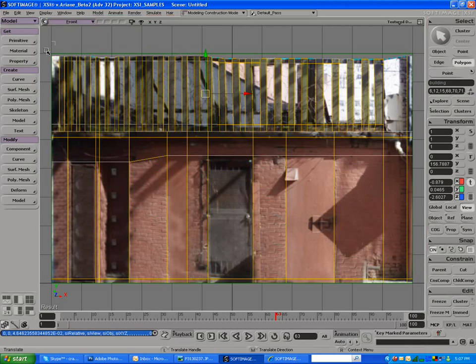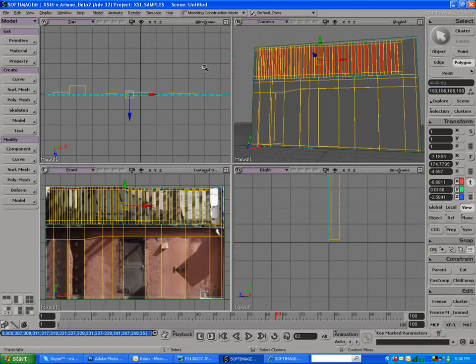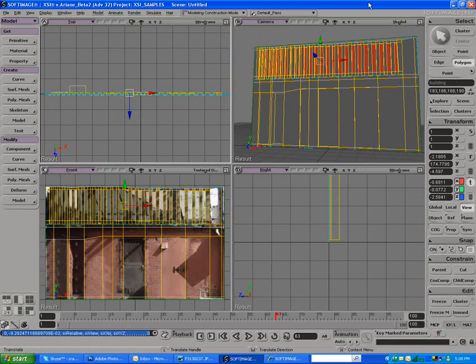So go to Control, and we'll just select over the whole lot there, and then we'll do Control Shift, get rid of the end one we want to ignore, and then also the top, and Control Shift on the bottom. We're in the Y mode, polygon selection by rectangle. We'll hit Control D again, and we'll move those back a bit.